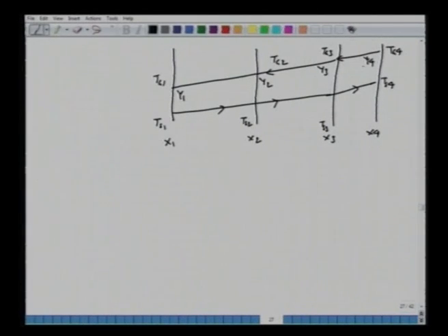All right. So before doing any calculations, maybe we should draw this and see what is given to us and what is not given to us. X1 is given to us. Let's put a tick here. X2 is given to us. All right, X3 is given to us. X2 is nothing but Xc, the critical moisture content, and X4 was given to us, but we said that X3 equals X4 because this is region 4. So all 4 moisture contents are known to us.